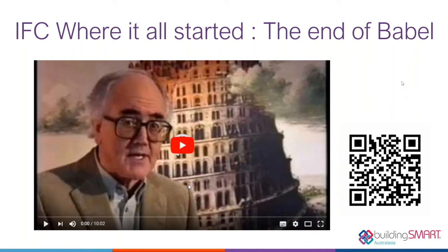Editing IFC files directly, there are very few software that actually natively read and write an IFC file format without a conversion from their own system. There is an application called Constructivity that I know of from Tim Chipman, who's been heavily involved in buildingSMART. And I think you'll find some other tools like SimpleBIM, which can allow you to post-process and edit and configure an IFC file even after it's happened.